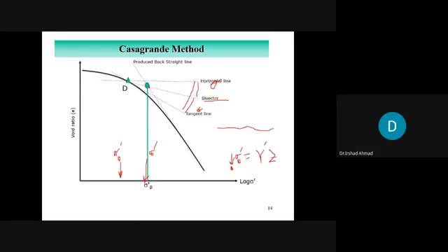Okay, now you got the idea. You learned at least 4 things on this slide. Number 1 is the pre-consolidation pressure, how to find it using the Casagrande method. Second thing that you learned, how to find sigma naught prime, and then how you would decide if this is a normally consolidated clay or an over consolidated clay. And one thing, when it would be curved and when it will be a straight line.